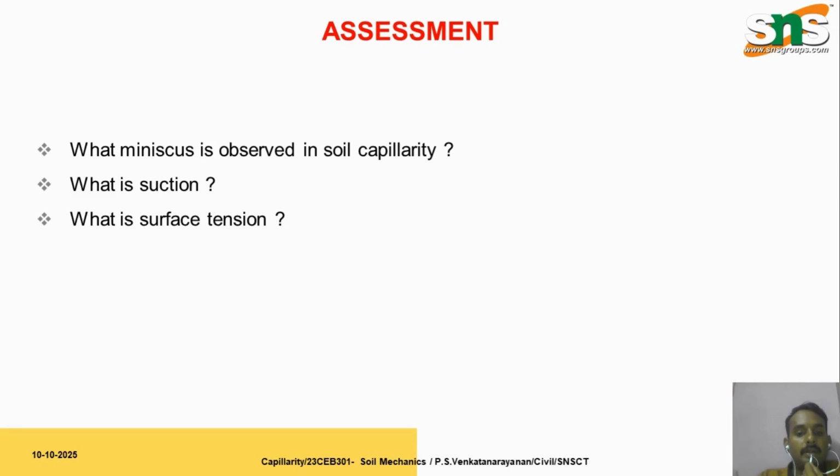This is very important in foundation engineering because if the foundation is within this zone, moisture variations can cause huge expansion, shrinkage or dampness. There are also several factors which affect the capillary rise of soil. First one is pore size.